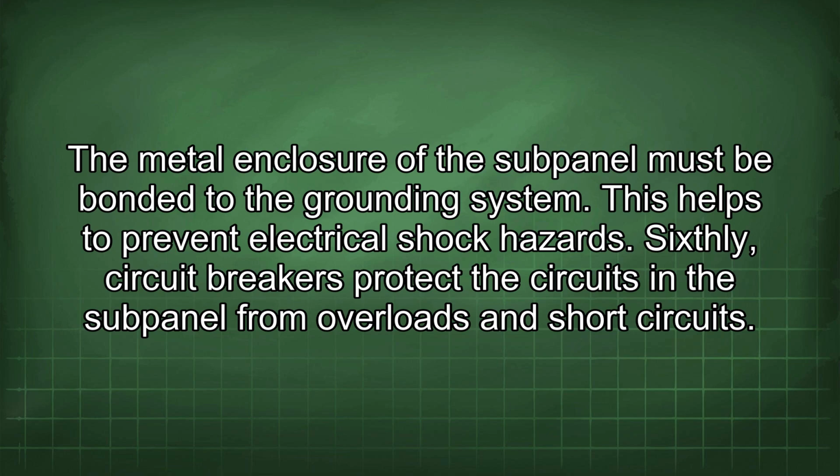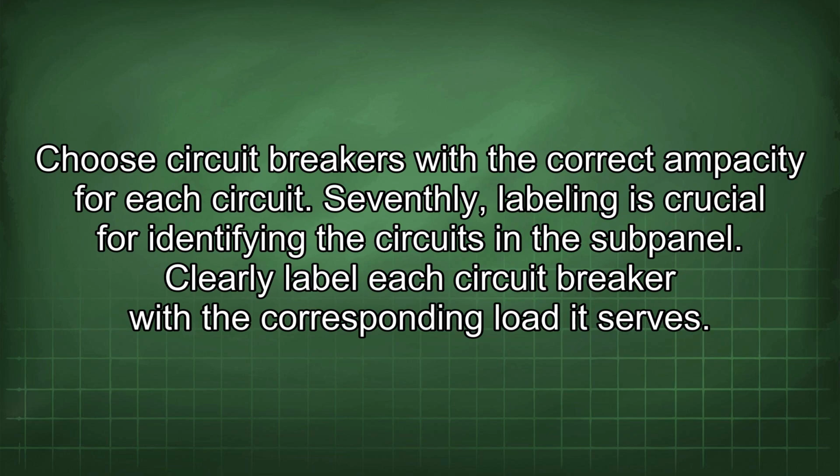Sixthly, circuit breakers protect the circuits in the subpanel from overloads and short circuits. Choose circuit breakers with the correct ampacity for each circuit. Seventhly, labeling is crucial for identifying the circuits in the subpanel. Clearly label each circuit breaker with the corresponding load it serves.